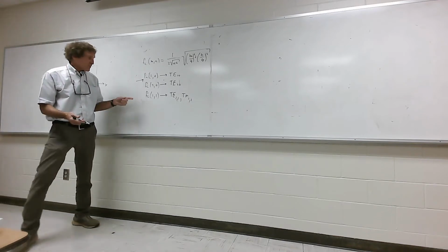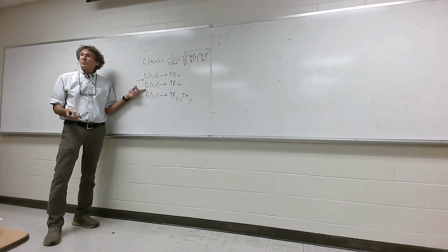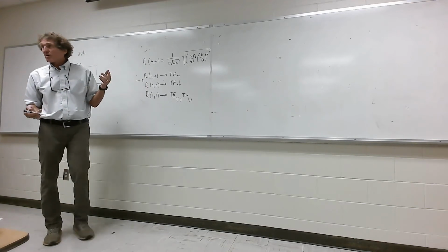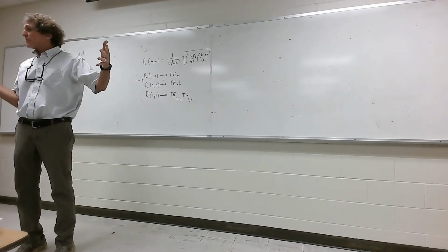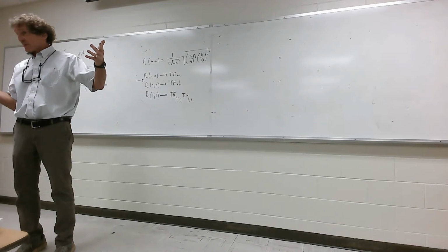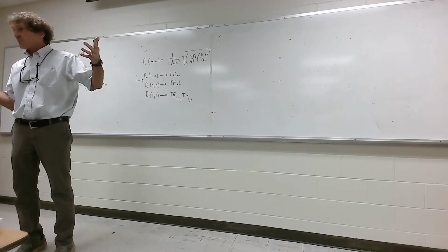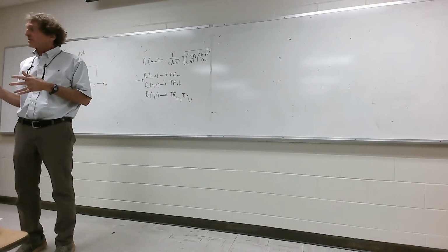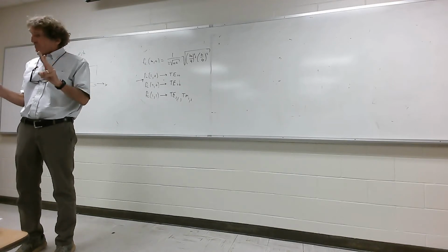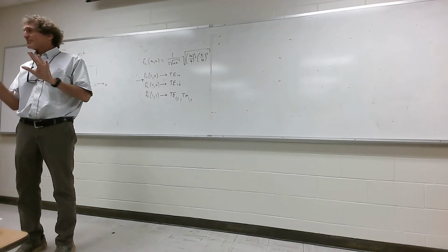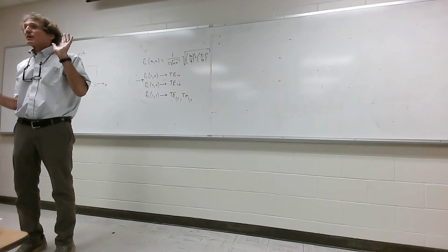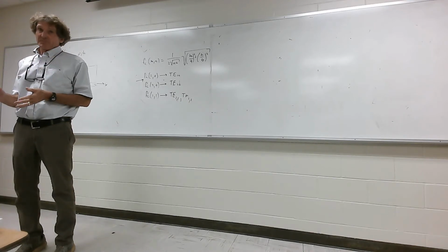If you operate in a frequency range above 2.0, now you have both the 1.0 and 2.0 existing concurrently, and no longer does your power go down the waveguide at the same velocity, because they're different velocities. Do y'all follow? It's real important you appreciate that fact. You never want two modes of operation. There are some exceptions, and I'm not going to get into that. But primarily, you never want it, in my opinion.